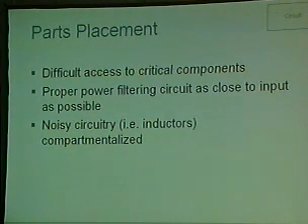An example of the parts placement I will actually touch on a little bit later too is there's two advisories that I recently released on USB hardware tokens, which if you're not familiar with them, they're basically little embedded systems that will store private data used for authentication and public key applications and things like that. I looked at two devices, and both of those devices used an external serial EEPROM, which are extremely common in the engineering industry. They're also extremely easy to read data out of.